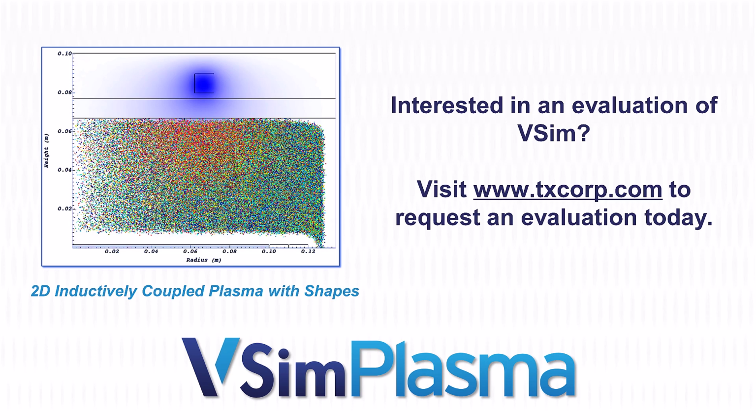Okay. We have another question. Is it possible to simulate effects of a Faraday shield between coil and plasma? The answer in short is yes. The specifics of how you would model that are tricky because an ideal Faraday shield would just completely block the penetration of EM fields into the plasma. However, a real shield has gaps and a finite depth. You can capture some of those effects with our code.